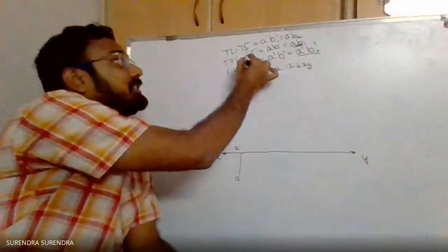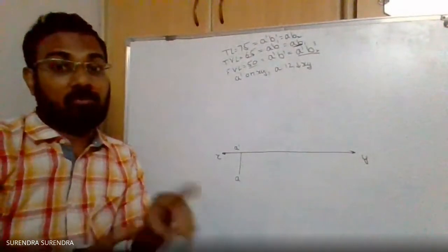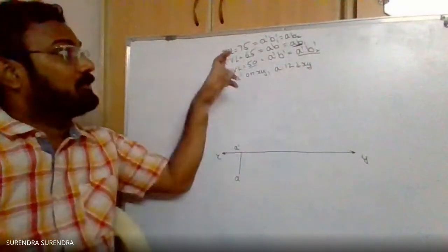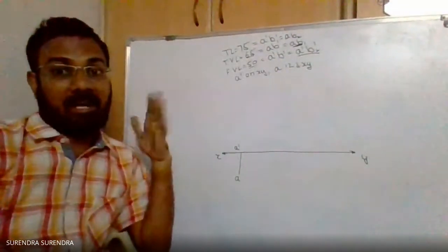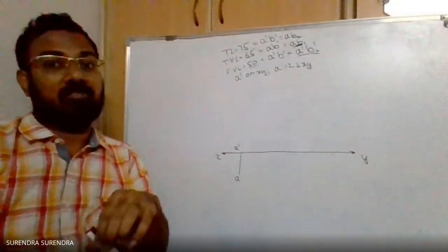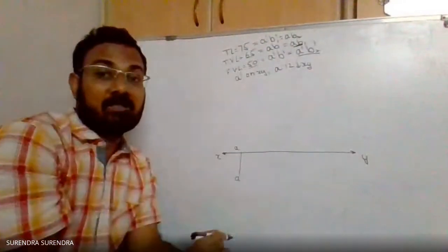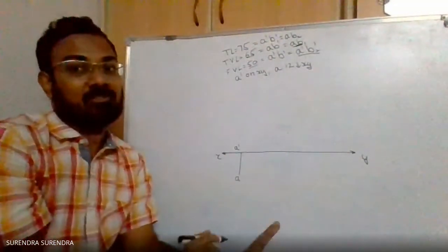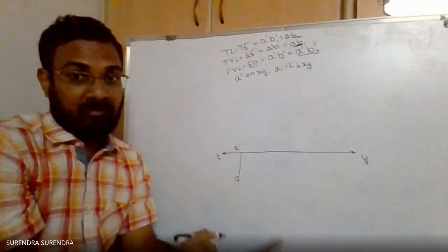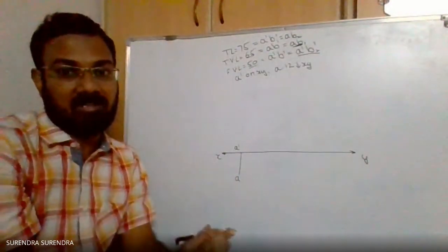So to draw a line, here you must remember the condition. We must know both its length and direction. Only if we know both can we draw the line. We know all these things, but angles we don't know. They are not given directly. So we can't draw any line directly. But we know the condition that AB1 and A dash B2 dash are always horizontal. So we know the orientation and length of the line. To draw a line, only if we know these two can we draw it. Otherwise don't start the line.